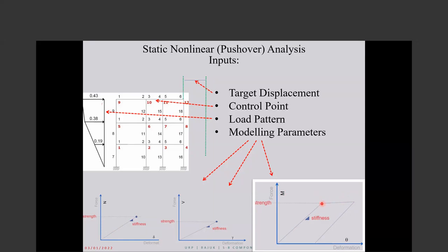The stiffness becomes almost zero and it becomes a mechanism. We expect the software to measure for us the amount of damage of this plastic deformation, this ductility demand. The ductility capacity of this is this capacity, but the ductility demand of this is so.